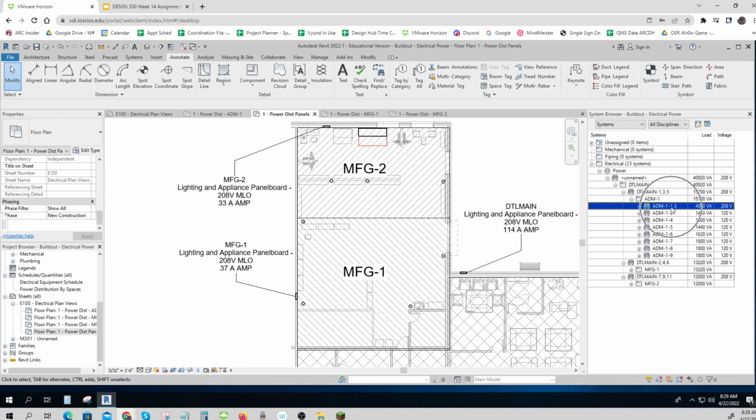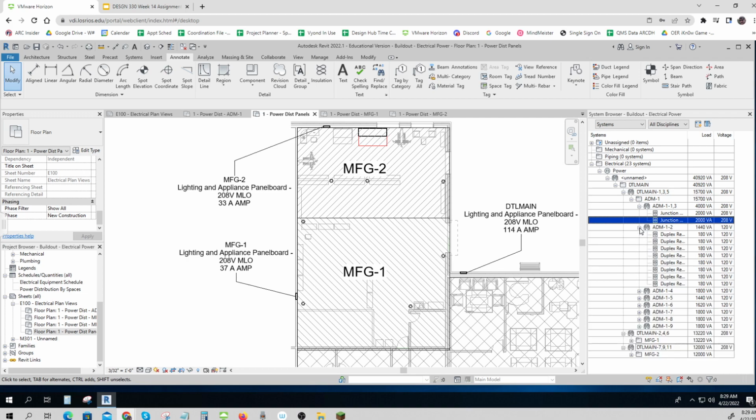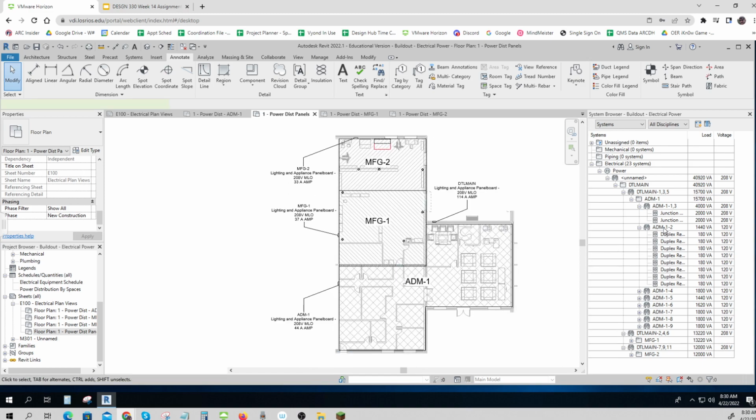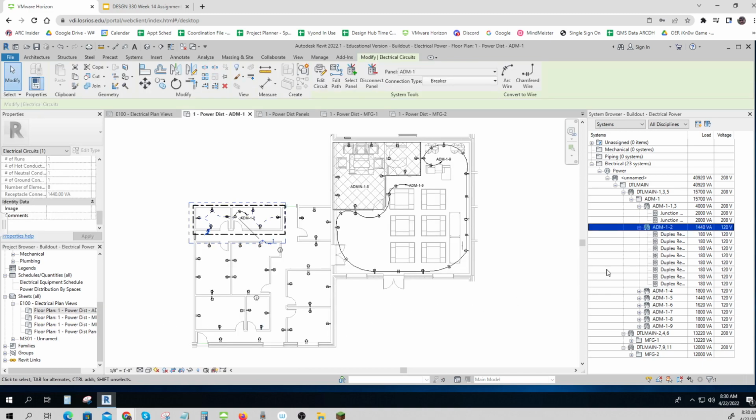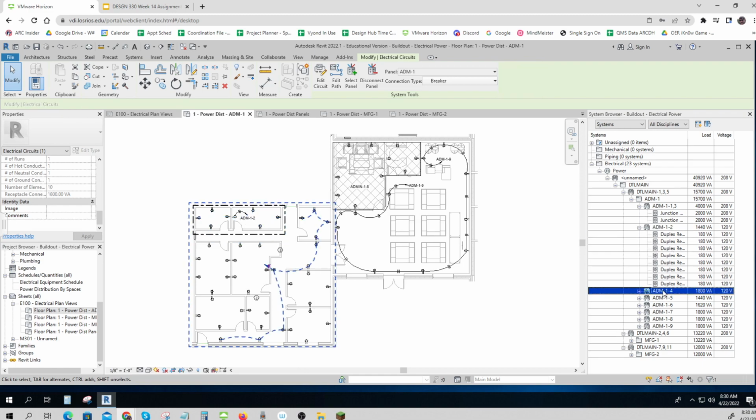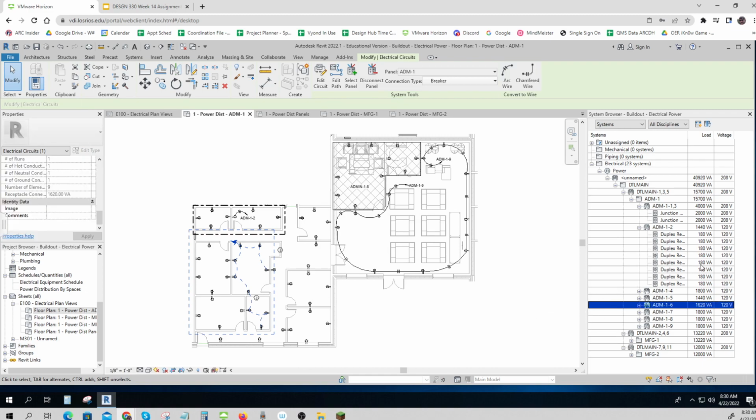And it tells me that on circuit breakers 1 and 3, I'm going to connect 2 junction boxes. And on circuit breaker number 2, I'm going to put 1, 2, 7, 8 of these little ones. So if I come over here, you can see which ones I've got. See how I can see? Isn't that cool? I can look and see what's wired into where using Revit. That is really, really nice. So it helps me keep track, and it helps me know what voltage I'm using.